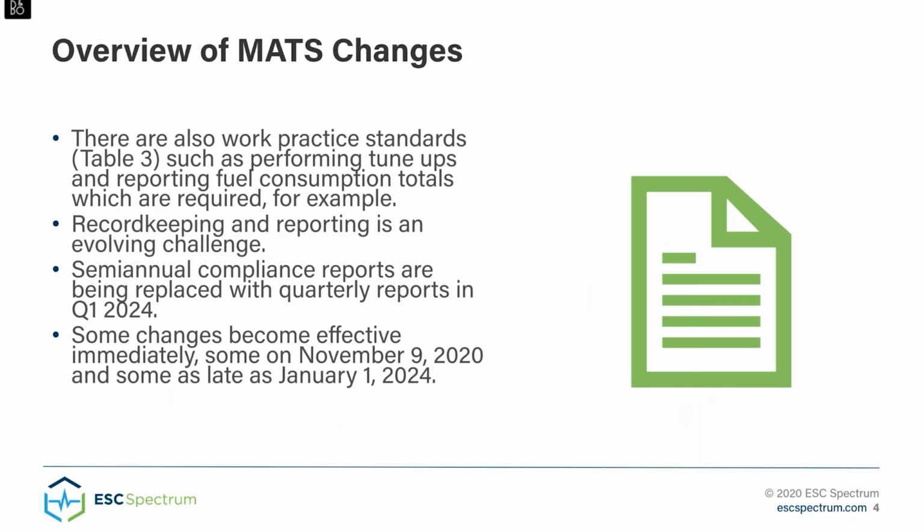Moving on, like I mentioned before, Table 3 associated with the regulation talks about work practice standards. These are things such as performing tune-ups of your boilers, reporting the fuel consumptions, things like that. And as with all regulations, record keeping and reporting is an ever-evolving challenge, keeping track of everything that you need to keep. The semi-annual compliance reports that you currently are using are being replaced with quarterly compliance reports, starting with the first quarter of 2024.